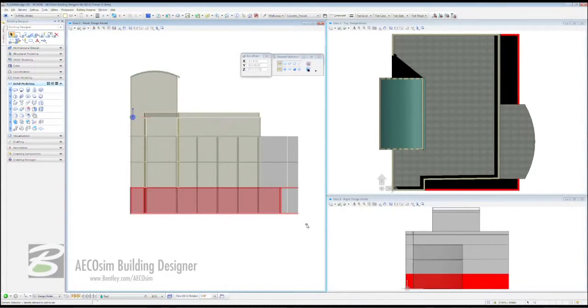So I'm going to come in here and do that, and I'm going to take out of this the 2 floors. So all I have is the bottom floor outer skin, and with that what I'm going to do is pass my cursor over it, right click, and say modify selected component. In that I'm going to look at the catalog type, and I'm going to say wall and click on OK.